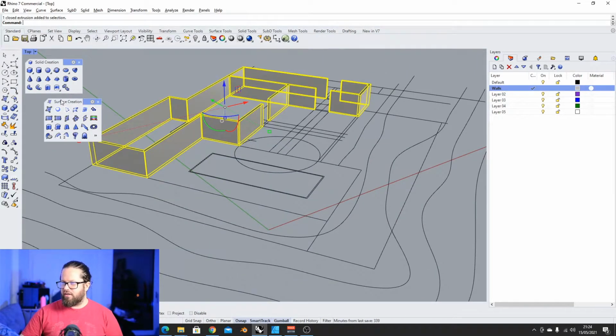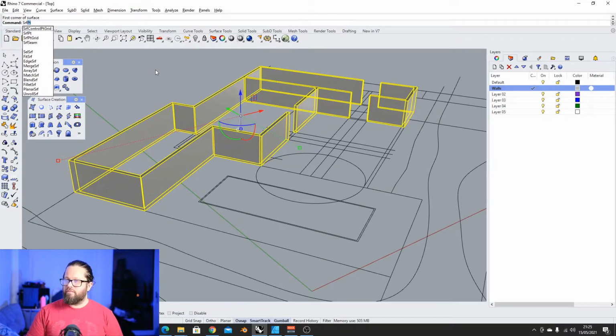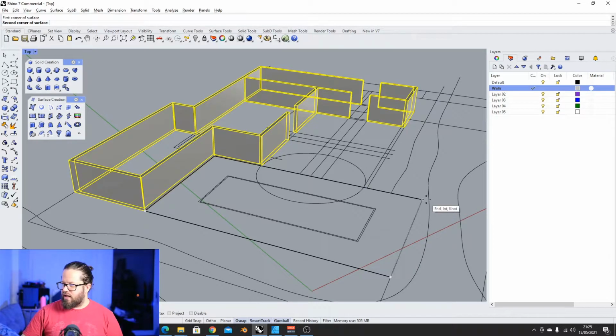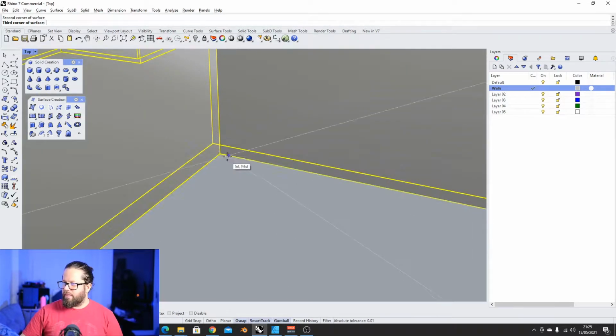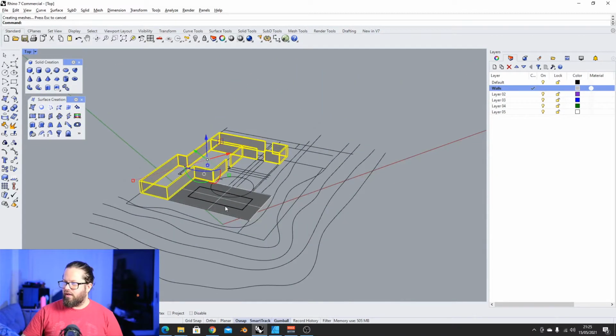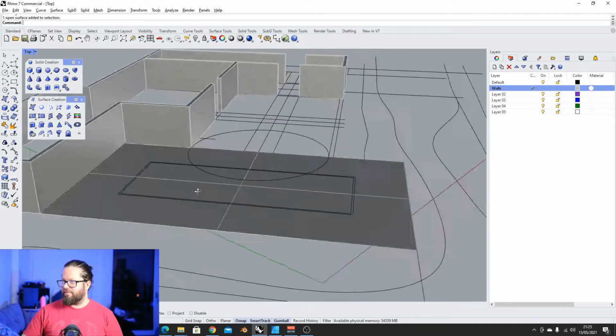So how could we create that surface? We can create it by this tool, Surface from 3 or 4 points. If we click here, we can also type SrfPt, then it's the same. S, R, F, P, T, and then we're already in the command. Depending on our snapping, we need to have our snapping on, and I put my snap point here on endpoint. With that, I can just select the endpoints of the line drawing. Here's a point you need to be careful. We want to be here in the corner and then here in the corner. And surface, yes, that's very good.